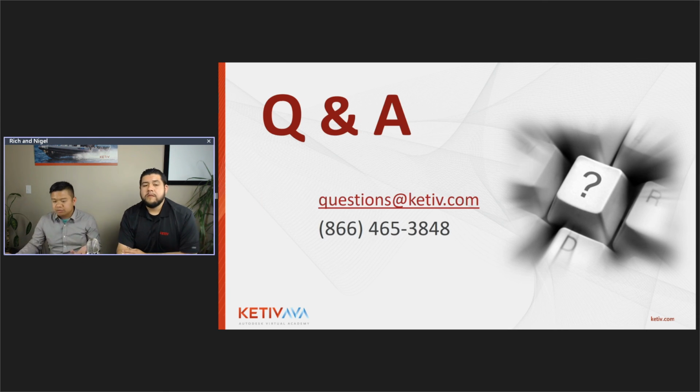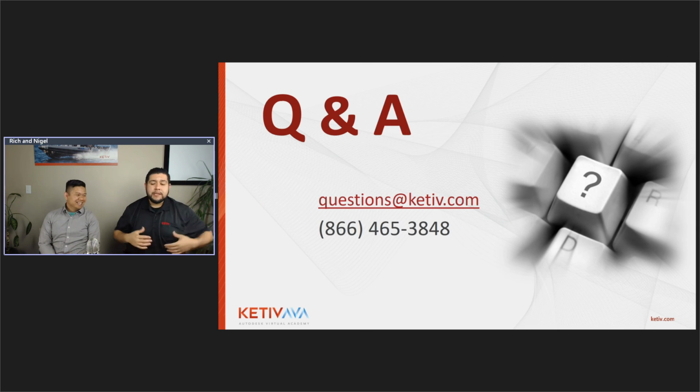This question comes from Greg. Does Inventor have capabilities to run FEA or simulate gas or liquid properties after you finish a design, or I guess during the design process even as well? So yes and no. Correct. Yes and no. It depends on the version of Inventor you're running. If you're running Inventor Professional, which most users are now with the change in how Autodesk is distributing the software, I believe most users have access to Pro. There is some FEA built into it.